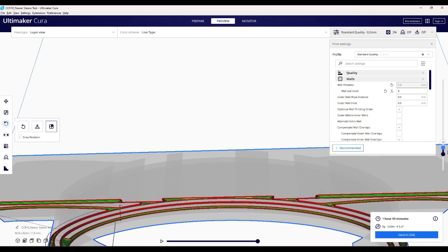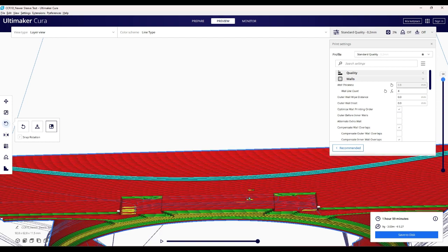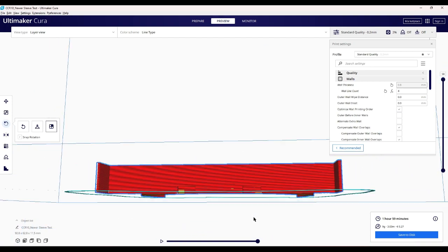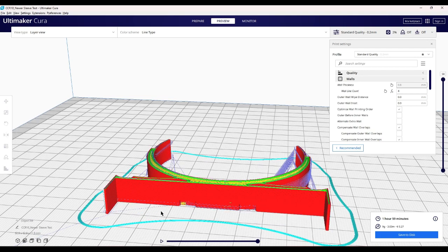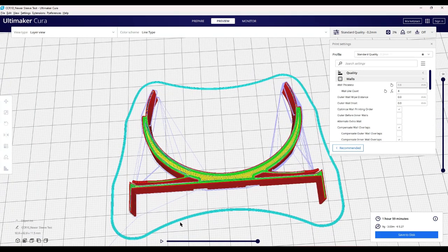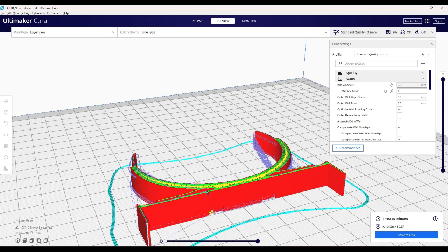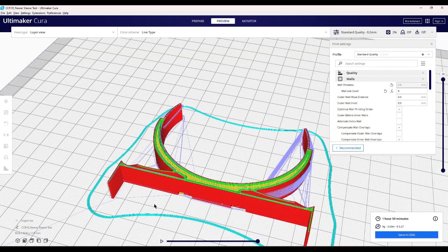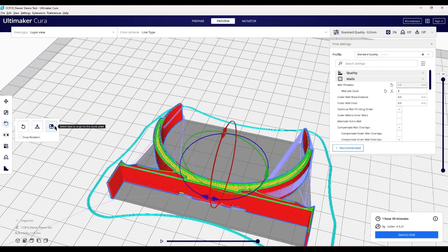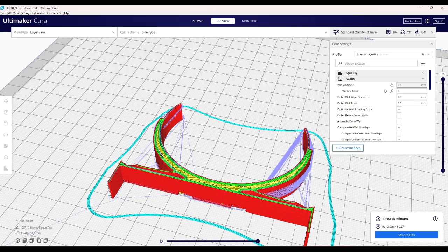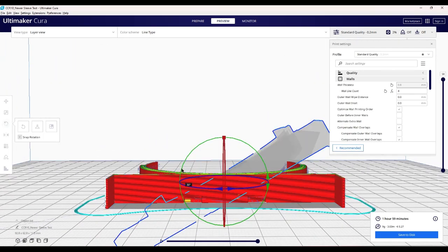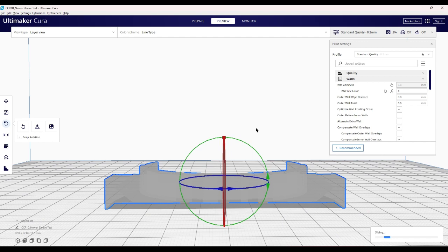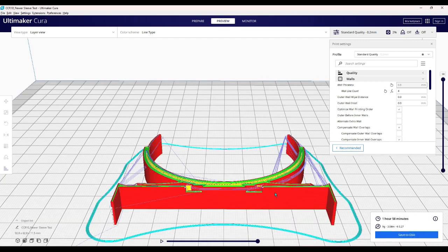That's so weird. Just random holes there. I'm gonna chalk that up to Fusion being stupid. I should probably print a brim around this, but I don't really want to. You know what? I'm actually gonna put this side on the bottom. The reason I'm gonna put this side on the bottom is so that I can put a brim on it.